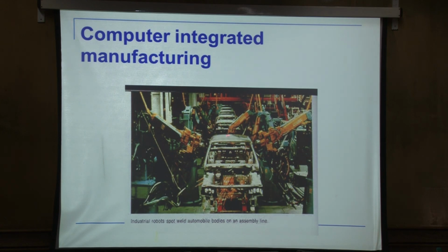And then they will come to the real world. Once they come to the real world, again without the car body, they will run the robot and then see whether it's working properly or not. Then they'll make a dummy of the car model, not using metal but using plastic or wood, so that if there is some error somewhere, it will not damage anything. After the third or fourth step, when everything is sure and they are sure that the cycle is optimized, only then does the real car body come and the actual assembly take place.